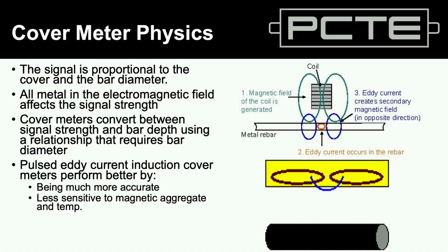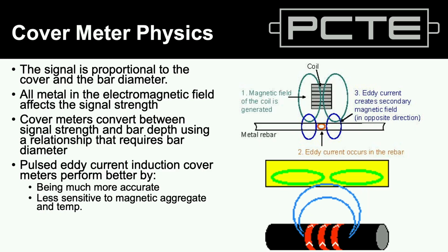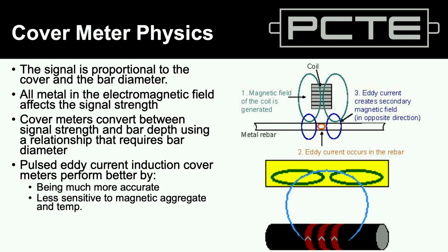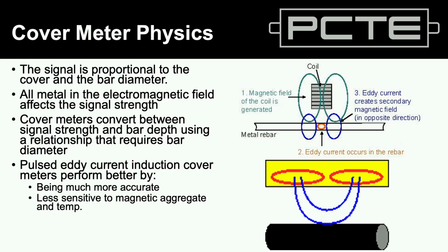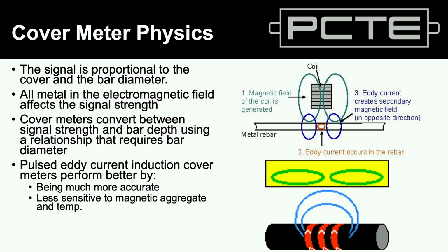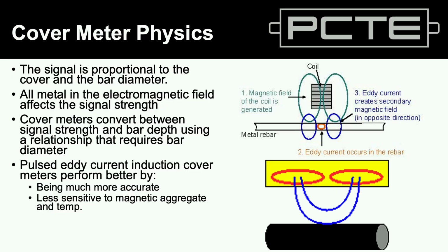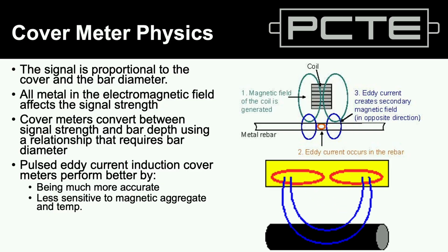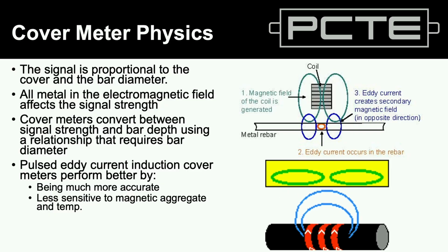And with the cover meter, there'll be a couple of inputs we have. We'll give it the size of the bar, so an assumed or measured bar diameter. And we may have a couple of corrections we can use if bars are close together, or we need to make some other adjustments to make sure the measurements are bang on. So if you're doing very critical forensic surveys, big, large-scale durability work, yes, you've got a non-destructive tool, but like with all non-destructive tools, you'll also want to have some destructive evidence, expose some bars, measure their sizes, check the depths, and use that to put in a really good input to get a really good output from your cover meter.